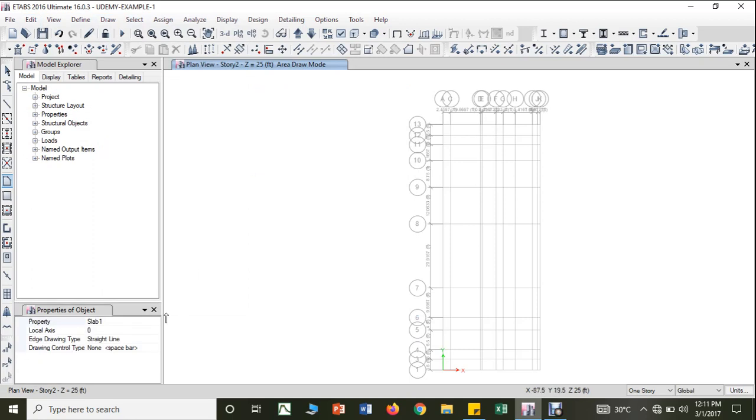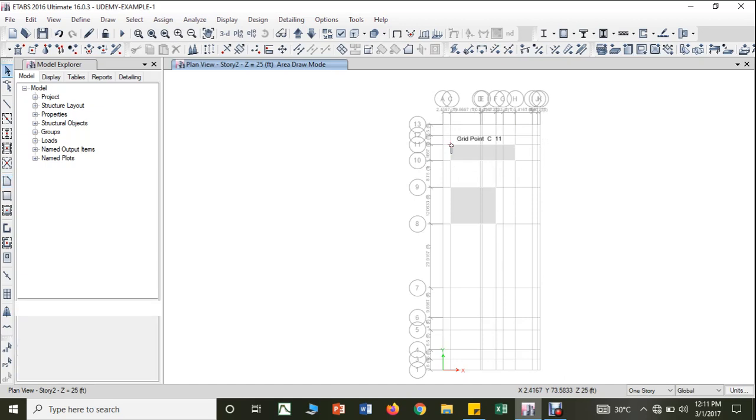When I choose that, you are supposed to choose what type of slab we have defined. There we have defined a slab of 6 inch, choose that. Right, now here also like this, start from this joint, go to this joint, go to this joint, and finally end here. Okay, so that is the option you have, quick draw walls, sorry, quick draw slabs. Like this. Okay, yes, so that is the option.